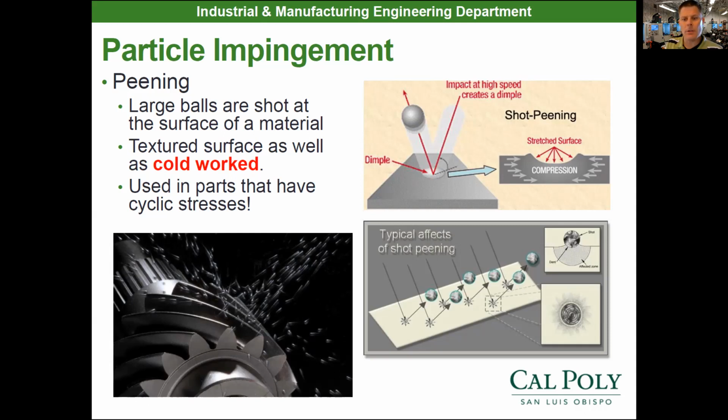So it's going to alter the surface by shooting little ball bearings or little beads, known as shot, against the surface of the part. What that actually does is it cold works the surface of the part, and it puts that surface in compression. So on parts that see a lot of cyclic loading, like when I used to build engines, we had our rods shot peened before we put the rods in the engine.